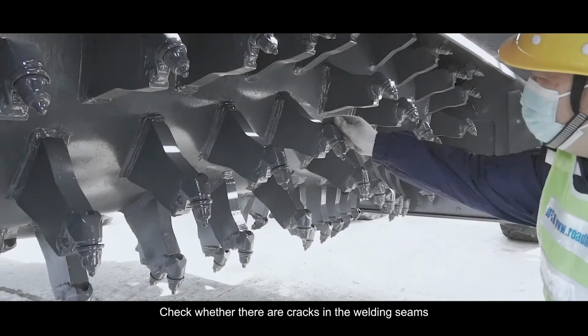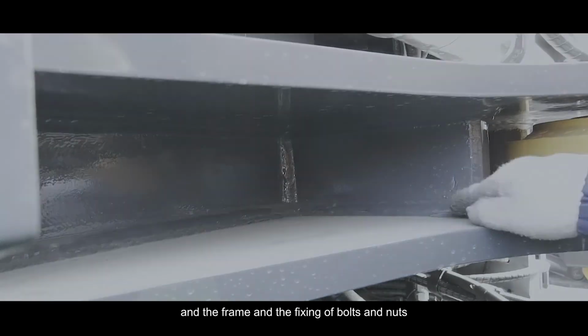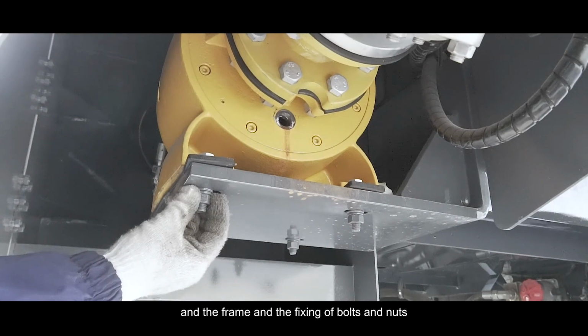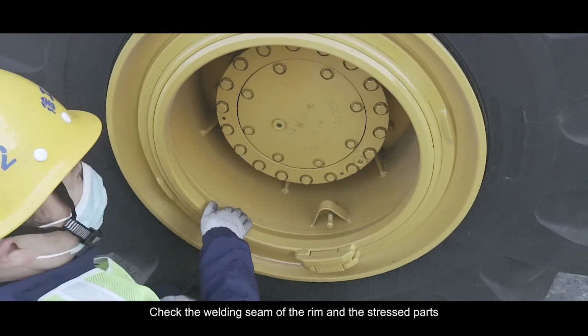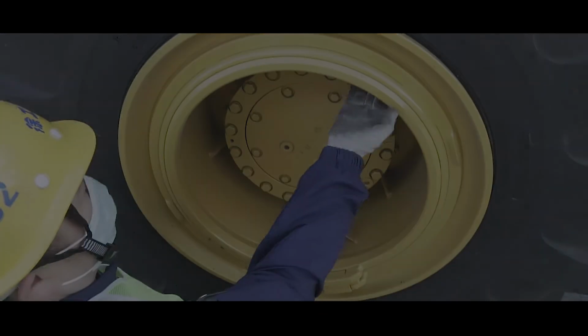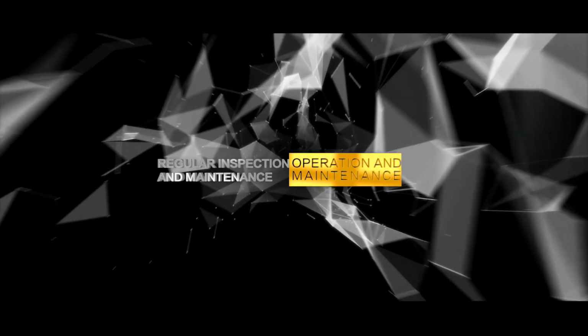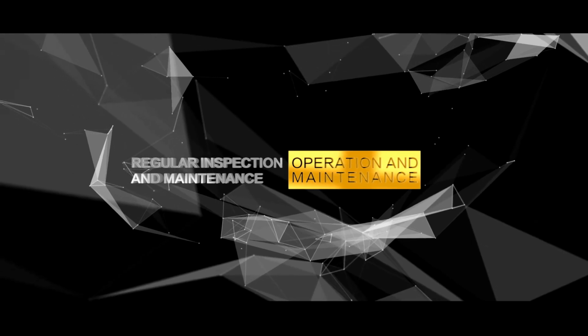Check whether there are cracks in the welding seams of the working device and the frame and the fixing of bolts and nuts. Check the welding seam of the rim and the stress parts and correct its deformation. Regular inspection and maintenance.